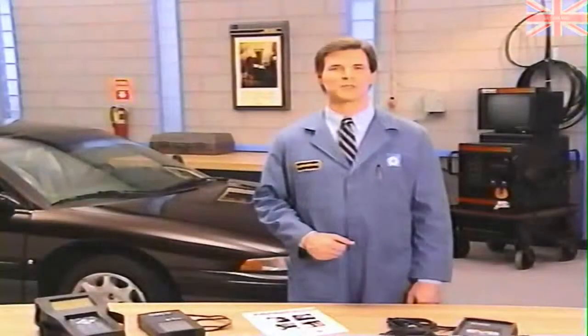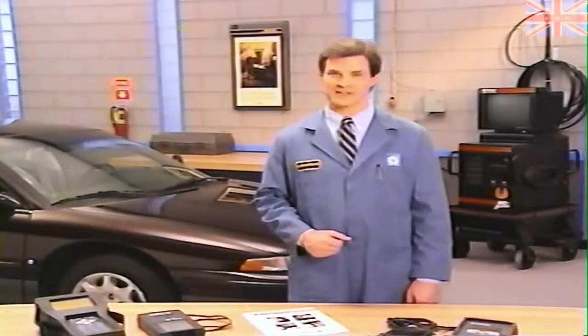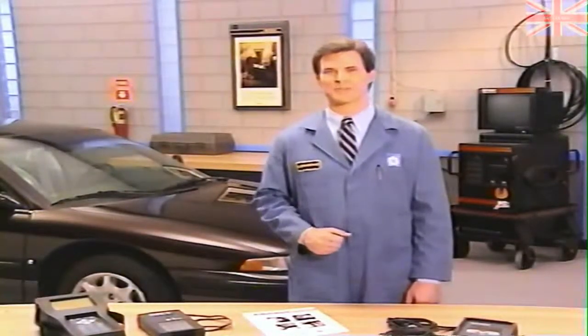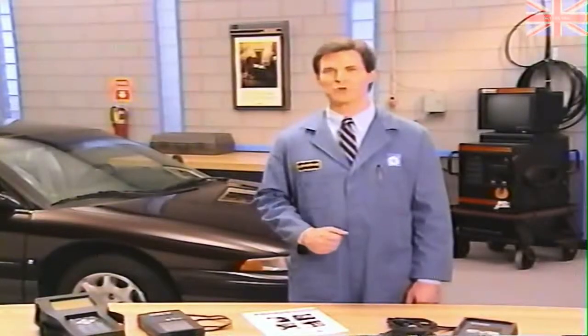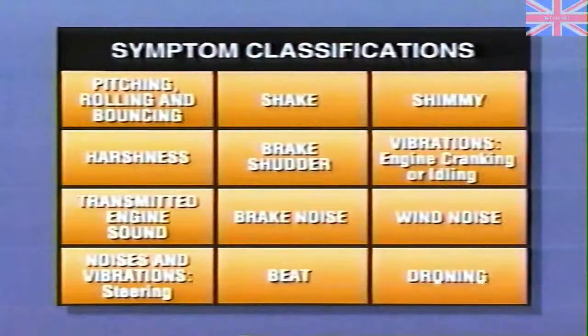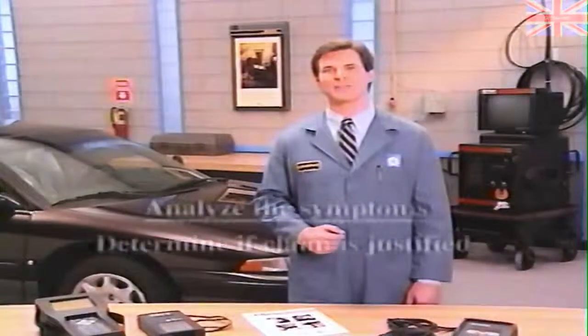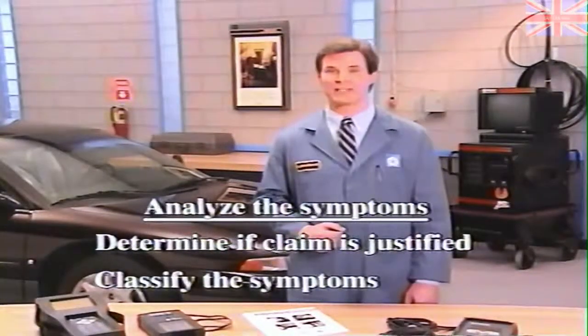The trouble symptom is definitely an abnormal condition, so the customer's claim is justified. Classification is the next step. Let's look at the symptoms. The body, steering wheel, and instrument panel shake vertically at a low frequency of 10 Hertz at 45 miles per hour. We also concluded that the problem is vehicle speed related. These symptoms are best described by the shake classification. We determined that the claim was justified and have effectively classified the symptom. We can now isolate the trouble.